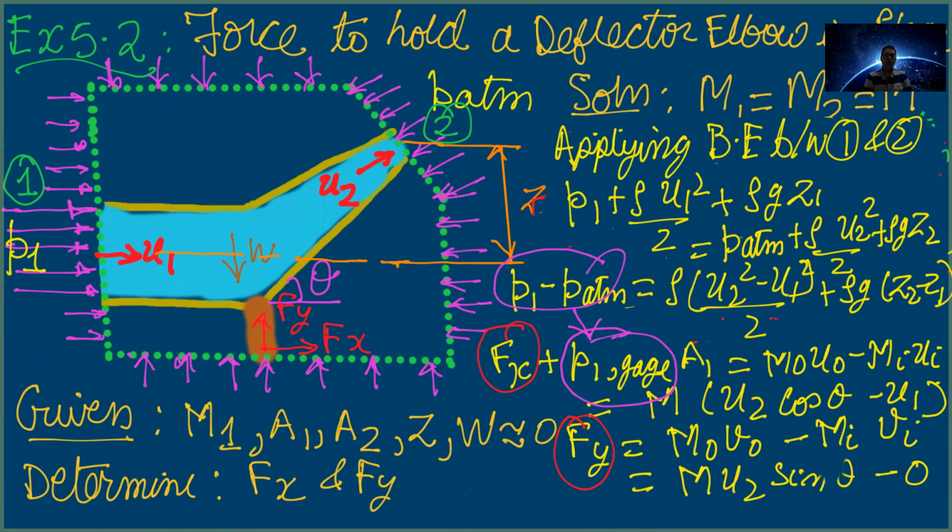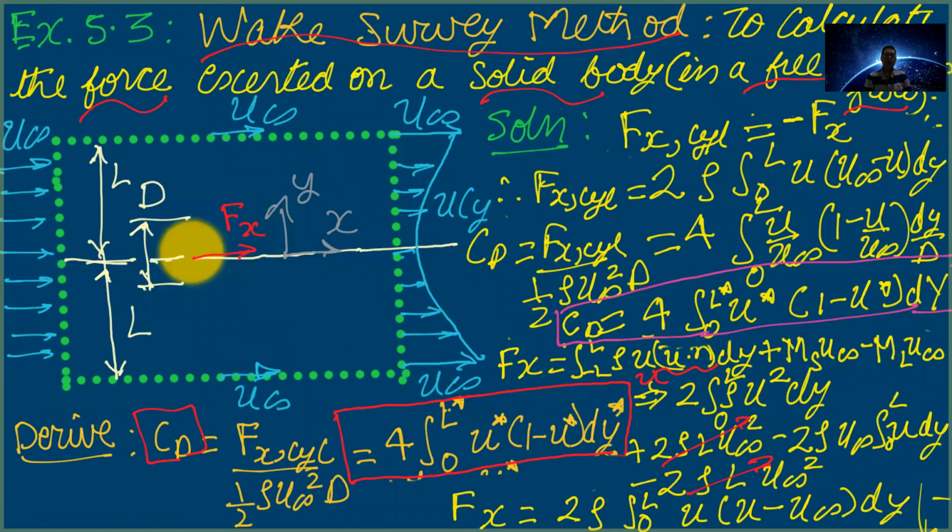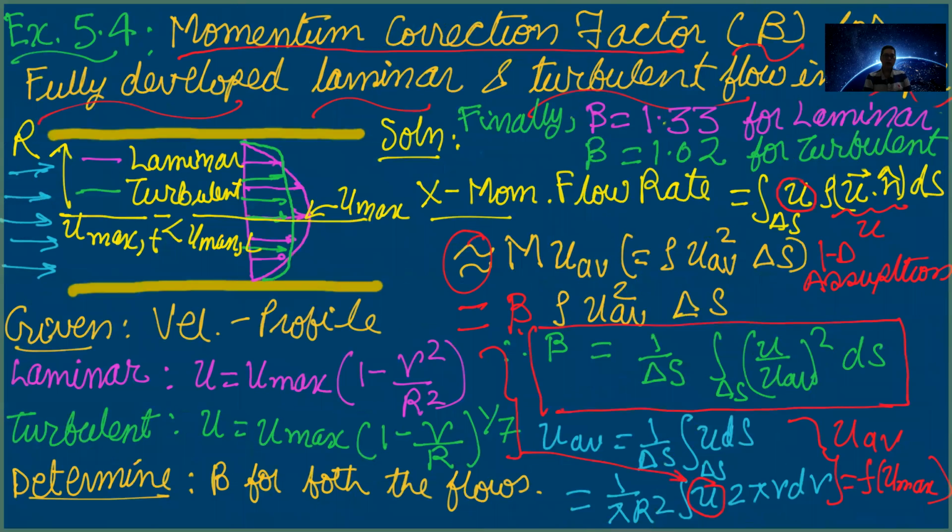And in the third problem, you are given velocity variations instead of a single value, and you have to apply mass conservation to calculate the mass flow rate on the side wall. So this was the key thing for this problem. And finally, I wanted to demonstrate that the algebraic equation that you use is an approximate representation where you made a 1D assumption, and I had shown the price associated with it.